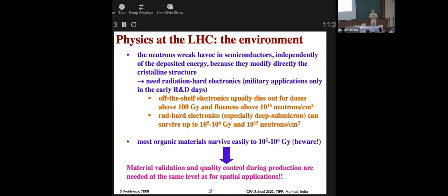The Kapton was used in the production of the boards to deliver the high voltage, produced in Russia by people who were helping to build this calorimeter. A supplier changed the Kapton without telling people, from one that had been tested to be okay for high voltage to another one that was not okay. And suddenly you break everything with such a small event. So this gives you an example of what quality control means.